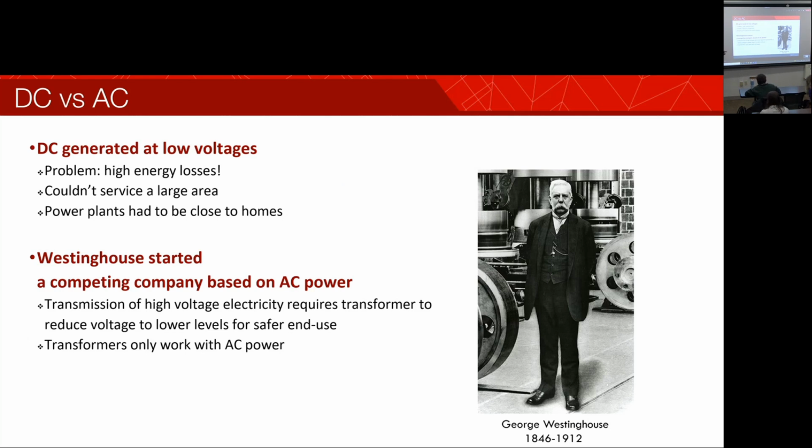Well, it's not changing the resistance, but the wire has a resistance, and if we have a high current flowing through that wire, we have high power losses. So they realized that if we were going to use DC electricity, we had to have the generator stations very close to where it was being supplied, because the long lengths of wire would have some resistance. So we had to think about how we can change the voltage.